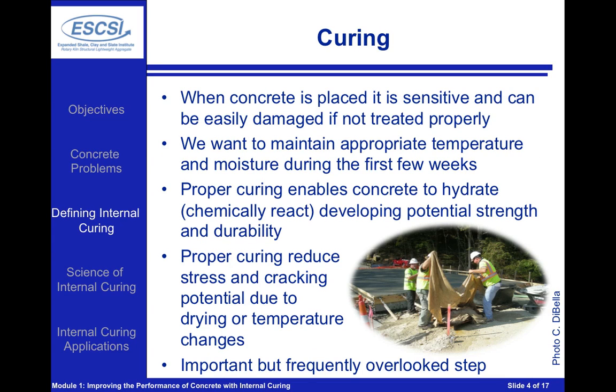So one of the things that we really want to keep in mind is curing is important, and we all know that curing is valuable for our concrete structures. When our concrete structures are placed, they're very sensitive at early ages to how they're cured, to the temperature, to the moisture, and they can be easily damaged if they're not treated properly. We know that it's good practice to try to maintain appropriate temperature and moisture for the first several weeks, and many times we see specifications where they tell us to moisture our concrete for a week or for 2 weeks.